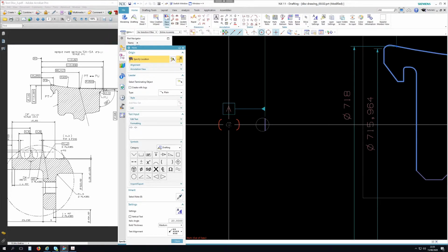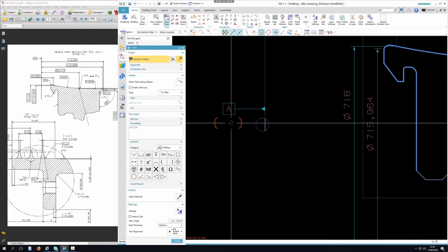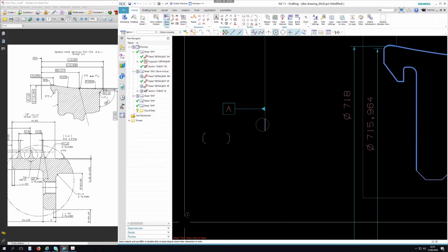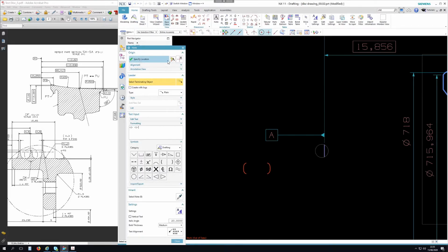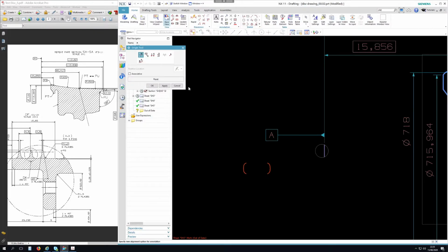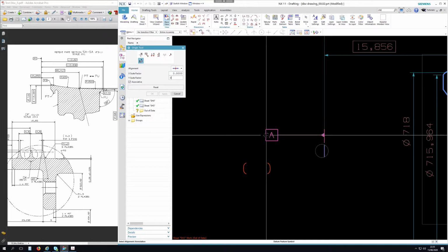So it's going to be somewhere around that size. Oh, maybe one more in the middle. So we could put that around it. Right, let's place that down to start with. What you really want is if you move this A this way or this way, you want this bracket to go with the A. So let's double click that again. It's got here location, origin tool. Let's pick XY, hit the associative, pick middle center. I think that wants to probably be 0 and 0. Let's try that.